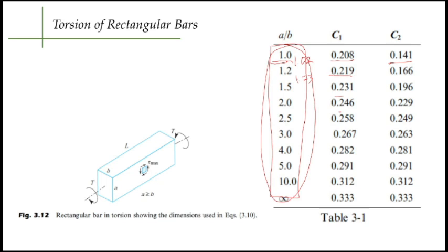Your median line is basically the middle surface between the inner surface and the outer surface. And then you have your angle of twist for your thin wall tube, which is TLS over 4 G A naught squared t, wherein your S over t can vary if your tube has different thicknesses, and your S corresponds to that certain thickness as well.